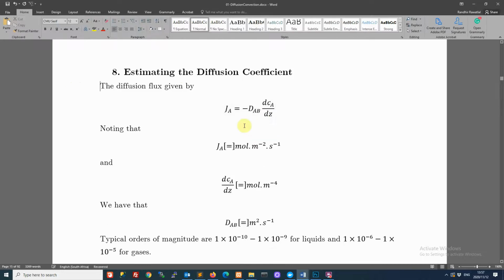On the other hand, in terms of diffusion, we can see that we have, number one, a gradient in concentration, and we'll show just now that's fairly easy to estimate. But on the other hand, we have this unspecified diffusivity. So this constant was introduced simply to grant us equality here. We would like to write a quantity which is the mass flux here, and we know that it's proportional to minus the concentration gradient. However, to convert a proportionality into an equality, we need to have the right coefficient here. So we need to know what multiplier to use for us to estimate this diffusion flux. And that's largely our focus in this session.